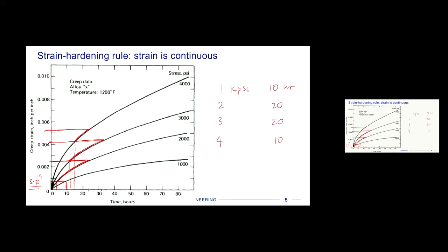All right, so these are all estimates, but in this case, all of our creep strain is continuous, so we just go to the highest value, read it off. It's between 0.005, 0.006, right? Let's say like 0.0052, right? Something like that. Okay. So that one's pretty straightforward.